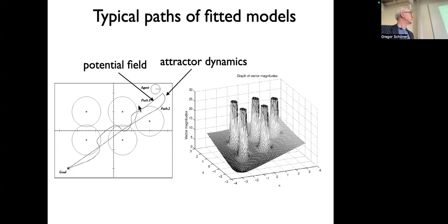You can see that it needs to run into this boundary where the obstacle contribution begins to take into account the obstacle. And once it's inside, then it will turn somewhat sharply as the gradient pushes it down and then go outside. And as it goes outside this obstacle, it doesn't really take the goal very much into account. That's why it turns so sharply. And then it enters the next obstacle, and so it goes against the grain. So intuitively, this is not a very good path. And it also gets even closer to the obstacle than the attractor dynamics approach. And that's intuitively why they say it's not as good in this case.